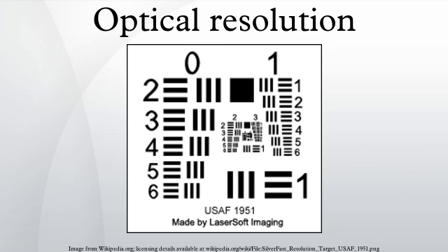If objects within the scene are in motion relative to the imaging system, the resulting motion blur will result in lower spatial resolution. Short integration times will minimize the blur, but integration times are limited by sensor sensitivity. Furthermore, motion between frames in motion pictures will impact digital movie compression schemes. Finally, there are sampling schemes that require real or apparent motion inside the camera that may result in incorrect rendering of image motion. Therefore, sensor sensitivity and other time-related factors will have a direct impact on spatial resolution.